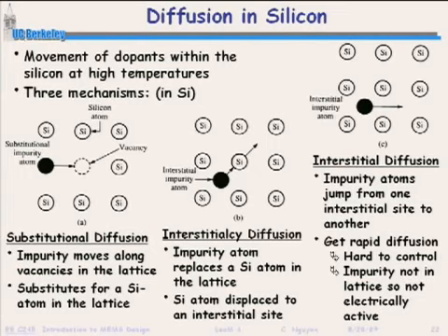They can't be moved around by field. Well, they can be moved around by field to some extent. So you take 243 for that. But all we're really saying is that at higher temperature, the number of defects in the silicon increases. And so the opportunity for a dopant to move around becomes greater. So you don't have to worry about the lattice vibrations. This is not a drift mechanism like carriers. This is just plain and simple diffusion. It's opportunistic diffusion is what it is. I don't know if I answered your question, but okay.